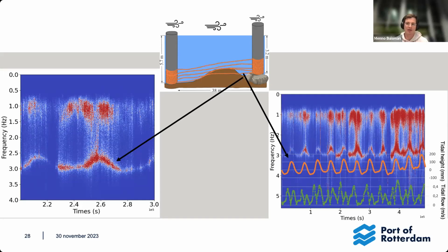And what I think is the main benefit of DAS is you can see phase information. And what it means is that, for example, if I see flow, I know it's really in water. Whereas with temperature, you cannot really separate the difference between, hey, maybe my cable is not functioning that well, hence it gets a little bit warmer, or it's not properly covered. So the phase information really allows you to tell what is going on there. Is the burial depth sufficient or insufficient? Is that why we get certain resonances?